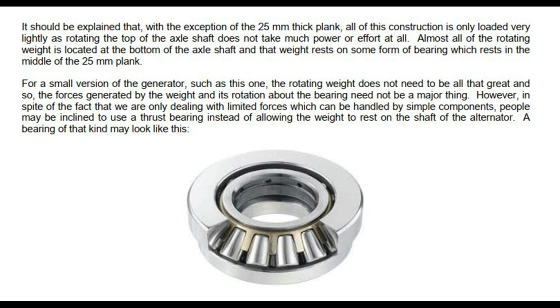Almost all of the rotating weight is located at the bottom of the axle shaft, and that weight rests on some form of bearing which rests in the middle of the 25 mm plank. For a small version of the generator, such as this one, the rotating weight does not need to be all that great, and so the forces generated by the weight and its rotation about the bearing need not be a major thing. However, in spite of the fact that we are only dealing with limited forces which can be handled